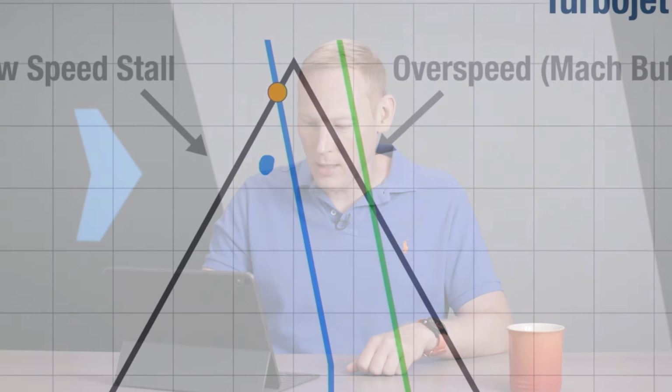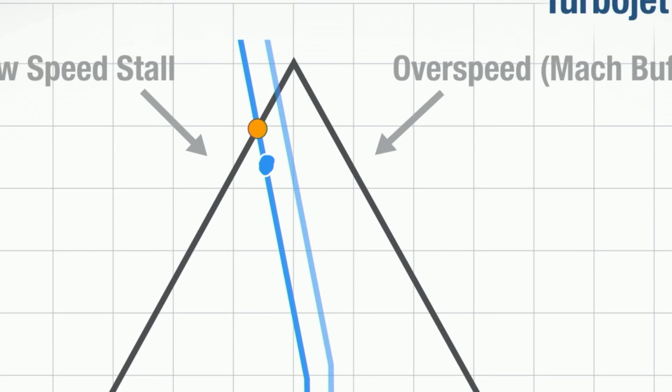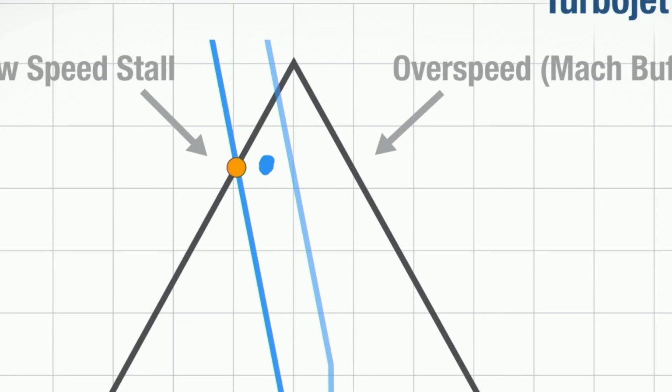And I know that at altitude, it's really cold, like 50 below. But the change from -60 to -50 still changes the air's density. And it will still reduce the power output of a jet engine. So if we go back to this drawing, what can happen there is as that temperature starts to warm, you'll notice right here, the speed we're flying, that's our maximum thrust setting. And so as the air continues to warm, if we maintain altitude at this temperature right here, the airplane would have actually started to decelerate and would now be at our stall speed.